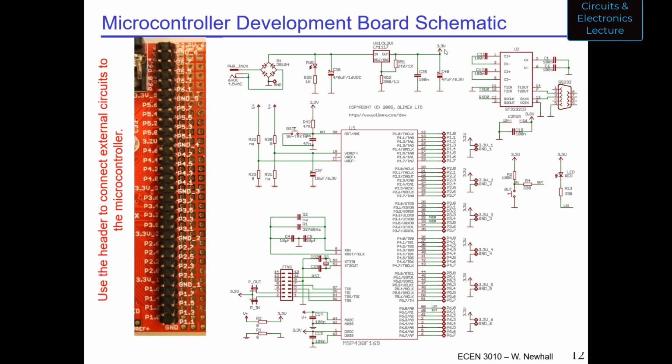And look, here's a node voltage. This is common. You'll see node voltages specified. So right there at that node, 3.3 volts. And then look down here at the right center, 3.3 volts, 3.3 volts. Those are assumed to all be connected. That's one node, all connected together, even though you don't see a line drawn between all of those nodes. Lots of 3.3s here. Same thing with ground.